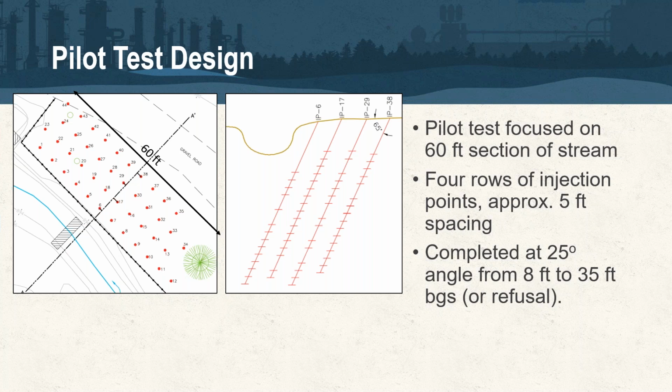One follow-up question that did come through during your answer relates to injecting through existing injection wells on the site. We cannot inject through existing cased wells when we're talking about overburden or even consolidated lithologies because we are injecting solid particles.